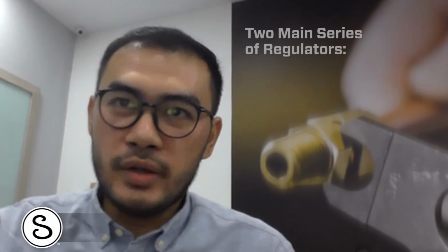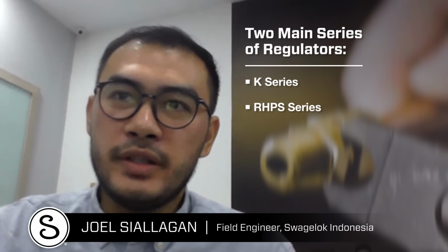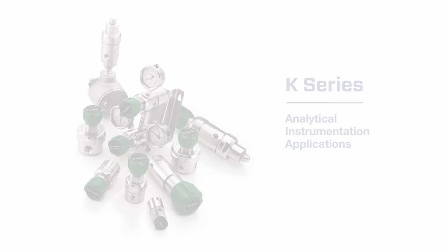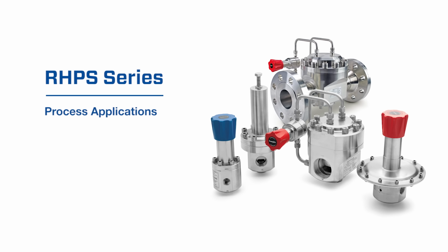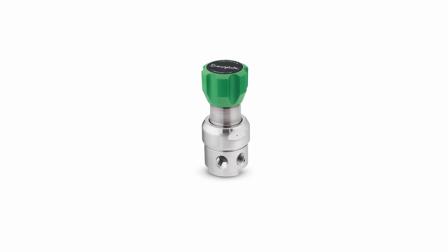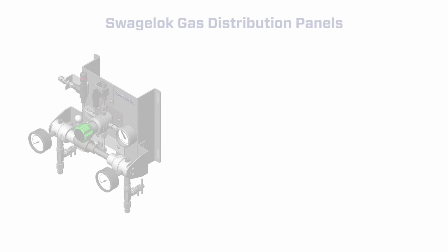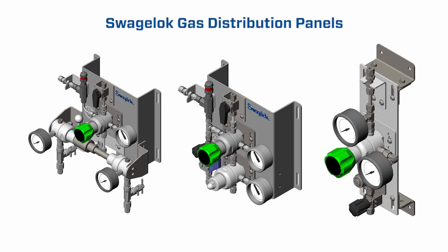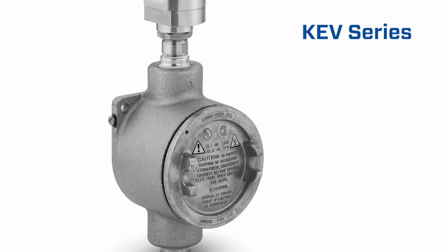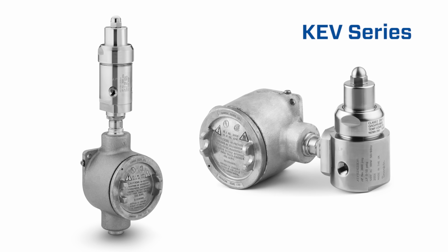Swagelok has two main series of regulators, which is a K-series and RHPS series. K-series is used usually for analytical instrumentation application, and RHPS series mainly for process applications. The smaller K-series regulators are typically used in analytical systems, in labs. We also have the gas distribution panels, which use the smaller K-series regulators. We also have the KEV, the electrical vaporizing regulator, which is used in labs to vaporize samples.